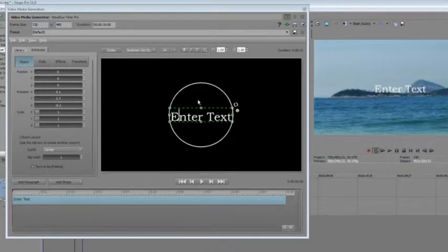And if I hit the middle of the circle or somewhere within the circle and just start moving around, you can see that I can do all of them at the same time. And as I said, this does take some getting used to get the exact settings you want. In fact, I kind of prefer myself to use the rotation tools in the properties area. So I'm going to set those all back to 0 just so you can see how I would do this if I actually wanted to rotate it by the numbers. And as we move along here, I'll do that a little bit more so you can see how it works. Once I've done all that rotation, I can click away and I enter back into the paragraph editing mode. Okay, so that's how we can edit the paragraph.